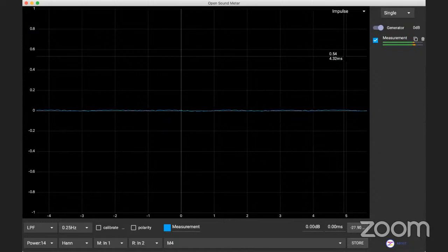Now, you need to basically understand what we are actually doing here. We are trying to measure the time that it takes for the audio to come from these speakers to this microphone. At the same time, we are seeing how long this speaker takes to reach this microphone. Then the next step is to align both the speakers so that we hear it as one entire system and not like two different speakers, or three different speakers rather. Before this workshop, we made sure that these two are time aligned. We have physically moved them to make sure that these two are time aligned, and I can prove it to you, hopefully if nothing has changed.